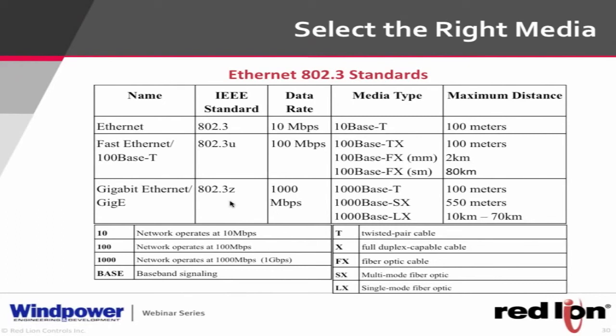Now, a gig connection is not what we always need. Most of the data on your network, 100 base speed is fine. So a 100 meg switch is what a lot of people usually get for this type of application because we're not sending a lot of data. We're just sending a lot of packets per second, but we're not sending really big packets. So we don't need a huge pipe. We don't need to pay a premium for gigabit Ethernet at every one of the ports because we're not producing a gig of traffic. So you buy a 100 meg switch with maybe a gig backbone. Your ring may be a gig, but the individual ports that connect to the end devices will be 100 meg.